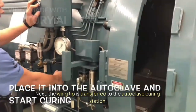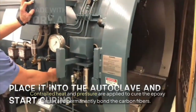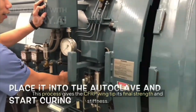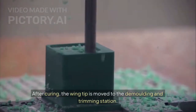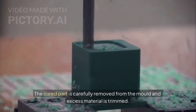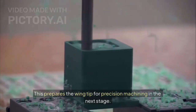Next, the wingtip is transferred to the autoclave curing station. Controlled heat and pressure are applied to cure the epoxy resin and permanently bond the carbon fibers. This process gives the CFRP wingtip its final strength and stiffness. After curing, the wingtip is moved to the demolding and trimming station. The cured part is carefully removed from the mold and excess material is trimmed. This prepares the wingtip for precision machining in the next stage.